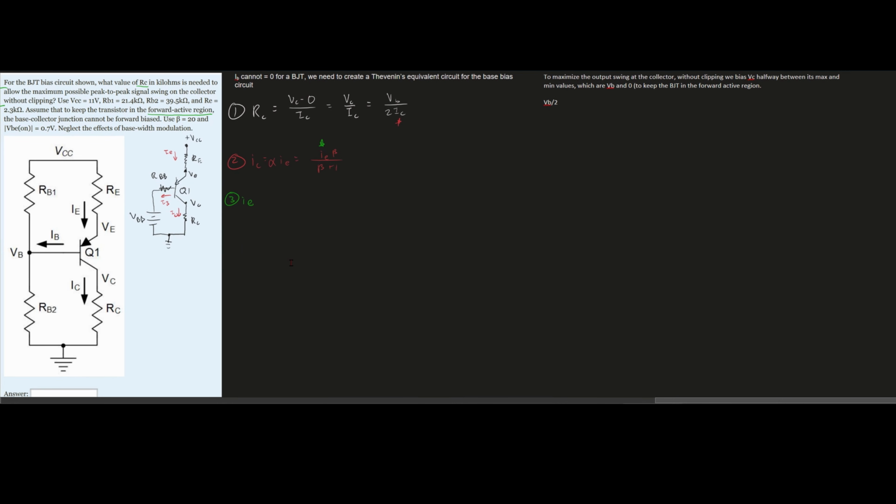Well, for our IE, we're going to want to write an expression around the voltage base emitter loop. And that's going to be like this part right here. We're not going to be solving explicitly for our IE here, we need to write an equation for it. We can say that our VCC, if we're looking at the loop, is equal to the voltage over the emitter part, right?